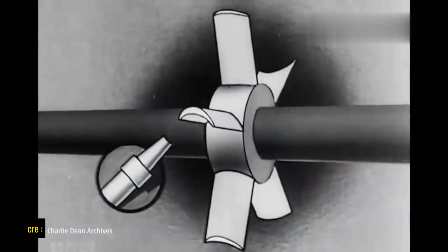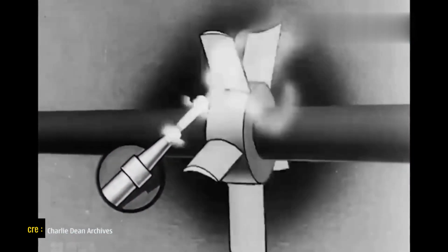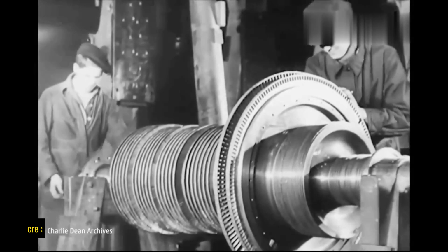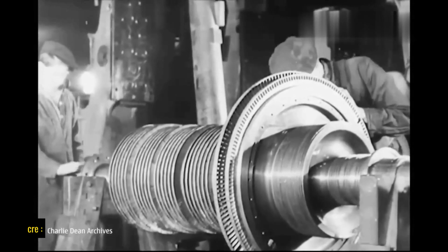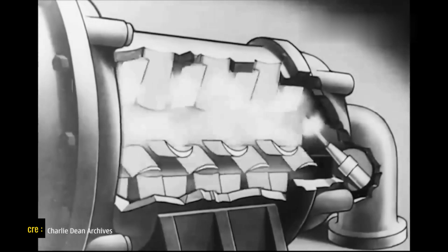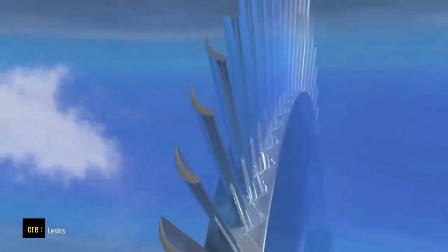Tesla observed that in traditional steam turbines, steam had to be forced onto the blades for the rotor to extract energy from the steam's velocity. In optimal operating conditions, the blades needed to be arranged to minimize the angle at which steam comes into contact with their surfaces. The purpose is to create a smooth steam flow, avoiding turbulent steam streams. Turbulent steam streams are quite undesirable as they waste a portion of the useful energy that could be extracted from the system. Worse, a turbulent steam stream moving in the opposite direction can diminish the kinetic energy of the smooth steam flow entry.